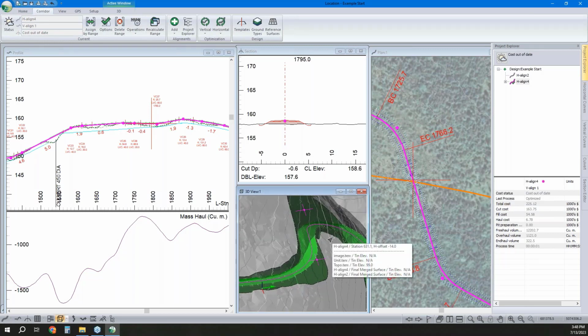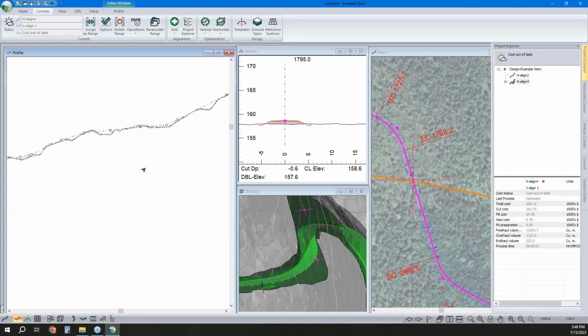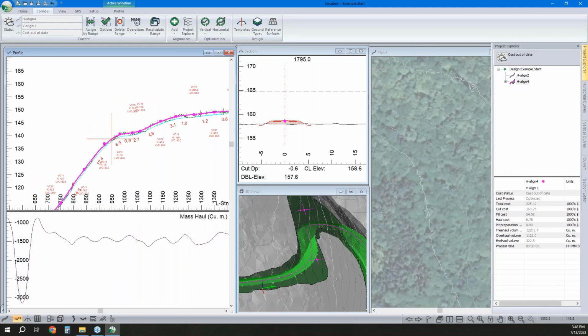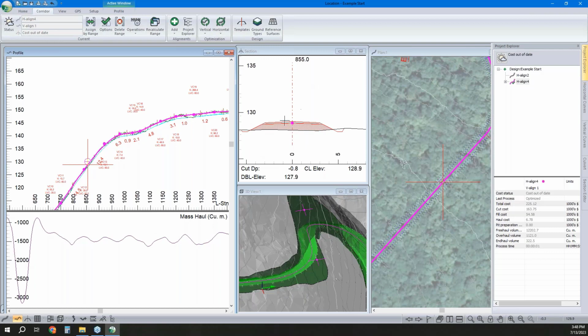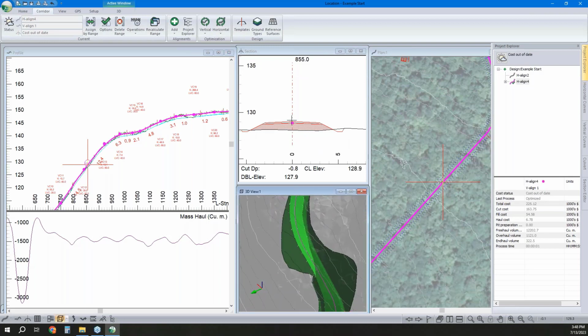So I'm going to use that as an excuse to talk about some stuff that I didn't even really discuss much. If you have something like this, where we've got our crown, and it's the default crown, but it's applied on a relatively steep grade, it's worth noting that when the rain hits that, it's not going to hit your road and go off to the side perpendicular to your road. It's going to follow the fall line of the combination of the grade and the crossfall.